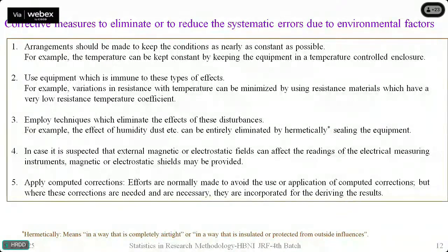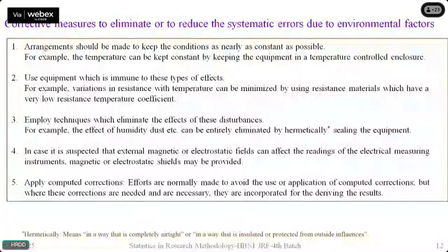of your equipment. Some equipment require calibration as a lengthy procedure. You cannot do the calibration every day; then once in a week or so you can do it. If your instrument is to be kept in a particular condition, temperature or pressure condition, maintain that condition. See to it that there is no gas leakage while doing the measurement. These are the precautions you can take and get rid of this systematic error.